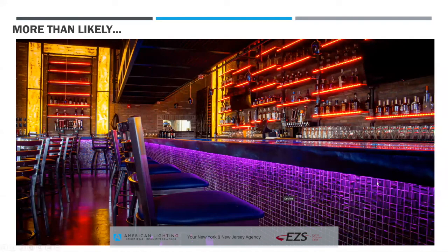This whole under cabinet bar is probably controlled as 1 unit. So that whole under bar is doing 3 DMX addresses. So you can get some pretty complicated looking stuff without using a whole lot of addresses and use a small control system, right? You wouldn't need a 100 DMX universe controller to control this bar. You could do it probably with a 128 address controller or half a universe or a single universe.